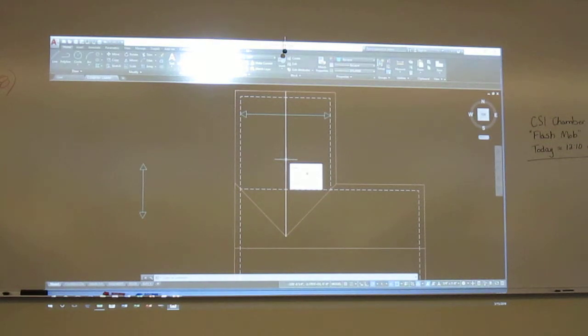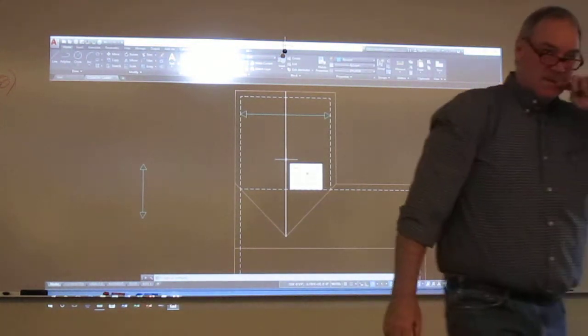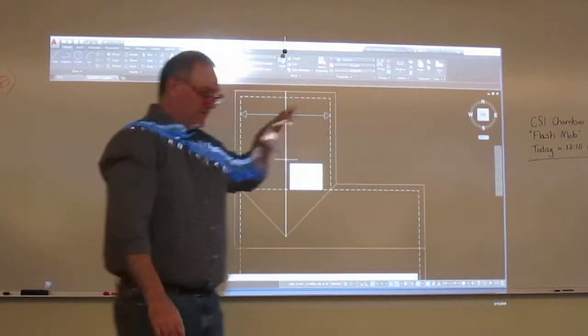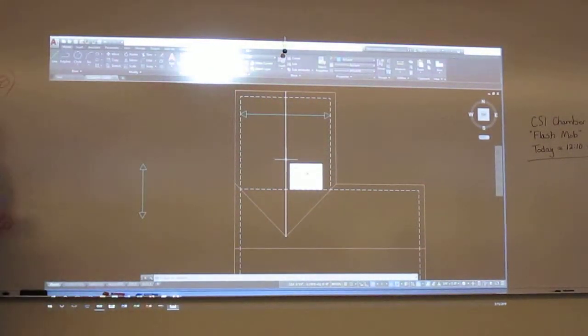Okay, now I didn't want this, I'm going to deselect it. It's changing right through that area. The thing you're not doing is including all the stuff you want to stay the same. It's got to be all the way inside the window. Remember, a crossing window changes on the edge. Everything inside is still selected.